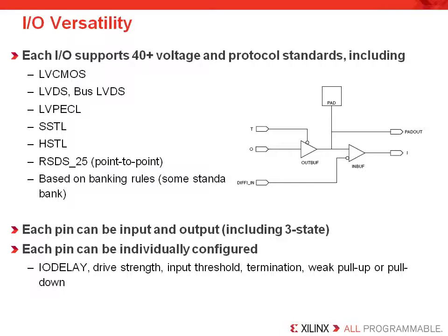However, note that to mix different I/O standards in the same I/O bank, you must be aware of the I/O banking rules. These rules apply because each I/O bank shares power pins for each of the input and output pins in the bank. Specifically, the VREF powers the input circuitry, and the VCCIO pin powers the output circuitry. So whichever I/O standards you group into each I/O bank, make certain that the input pins can support the same VREF, and the output pins can support the same VCCIO. Now, as an FYI, this is easily planned by using the PlanAhead utility included with the ISE software.